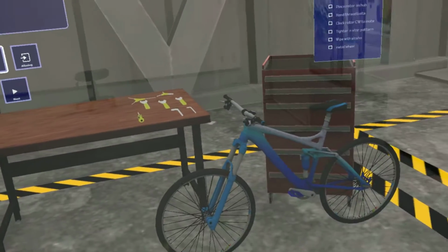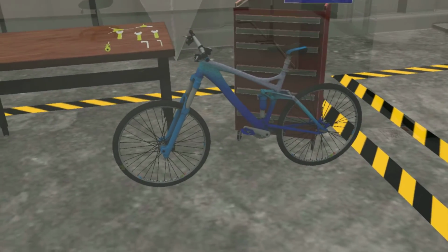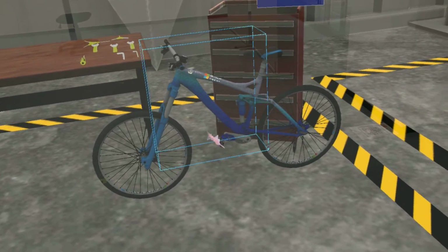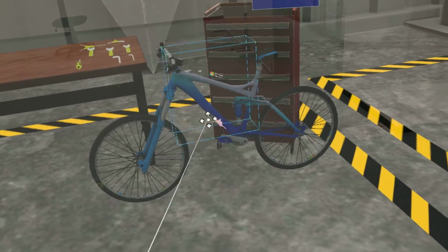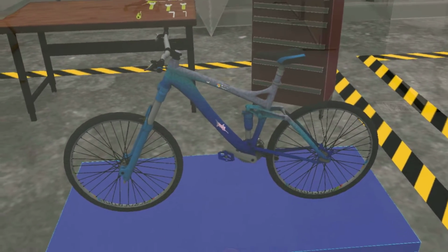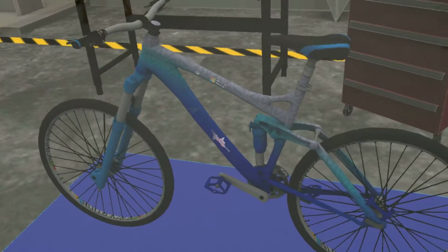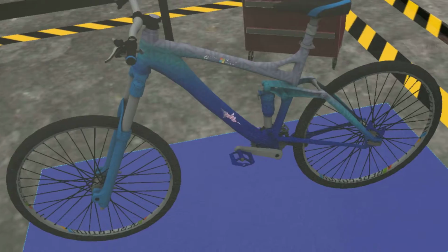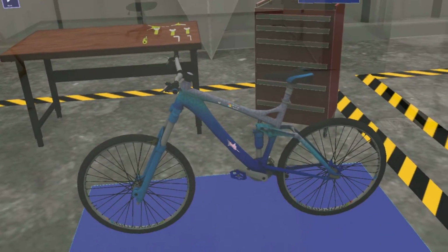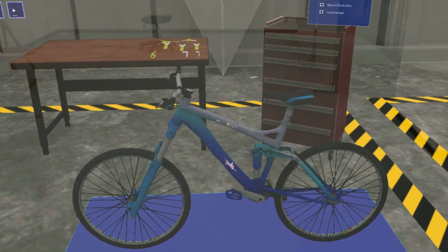Your next task is adding one of the decals to the frame of the bicycle design. Go ahead and select the decal, then drag it to the bicycle frame to apply it. See how the frame is interfering with the decal? This is called Z-fighting. Z-fighting typically happens when two surfaces on different objects resolve to the same Z-depth value. It can be particularly noticeable with motion, where the distance between viewer and holograms are changing.